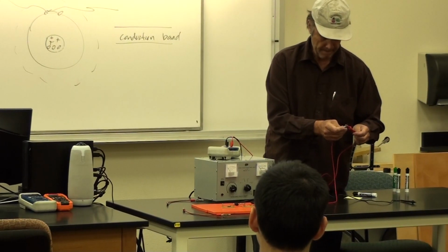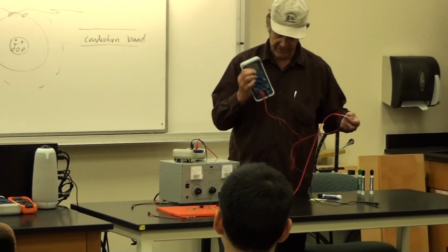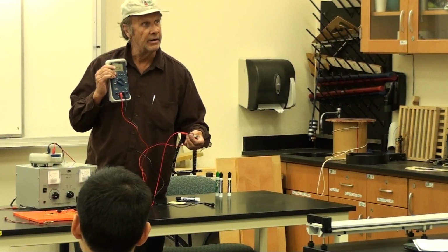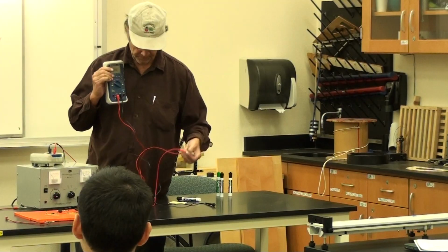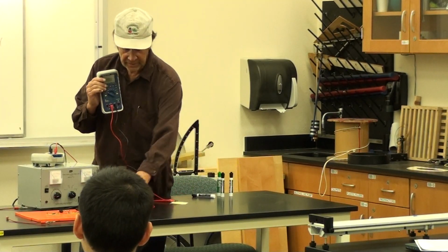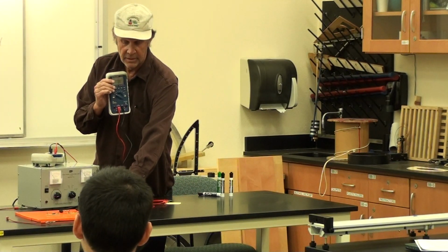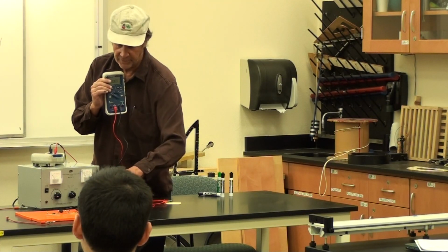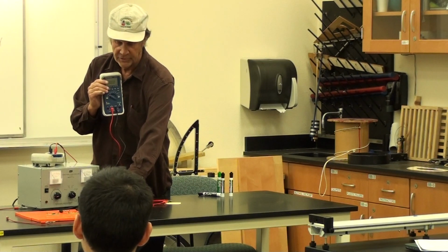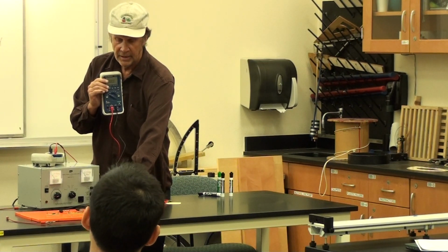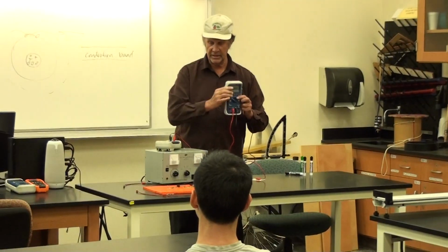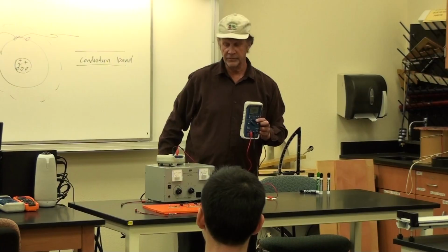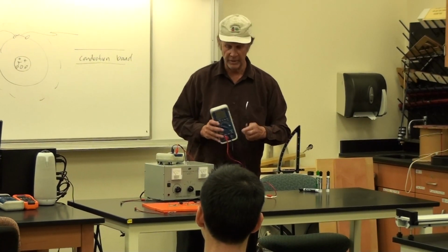Instead of going straight to the resistor, it goes to the hot side of the current meter. Then the negative side goes to this point over here on the circuit, where we had the wire directly hooked up before. Essentially we're putting this meter in series with these two resistors. This is the difference between what we call a series measurement and a parallel measurement.